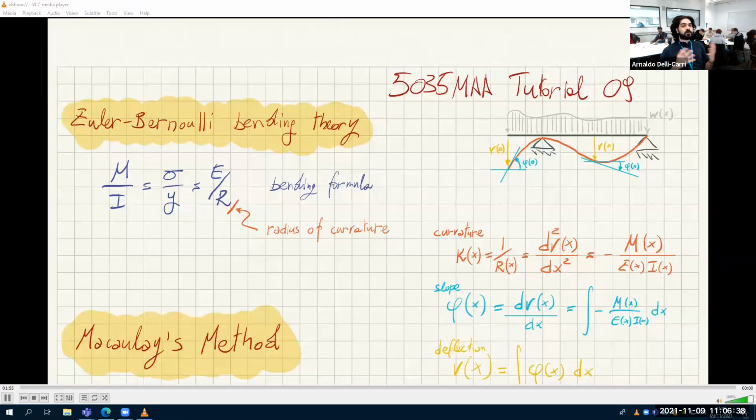Now, bending is the most complicated of them all. Well, apart from possibly torsion of non-circular sections. Because torsion of circular sections, the sections always remain plane. So you only have to care about the angle of twist. But if the section is non-circular, say if you have a square section and you're twisting it, then you also have axial strain, because you have a warping of the section. So you have to calculate the warping function. That's quite an advanced concept. You'll see, you probably do this in year 3 or year 4 if you go that far.